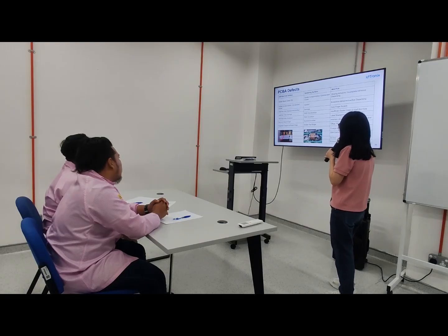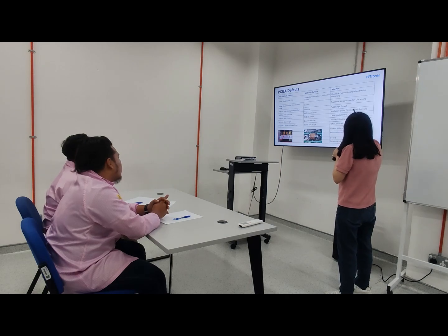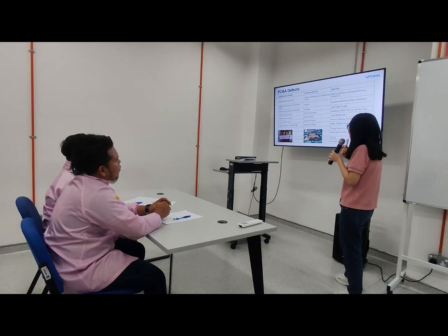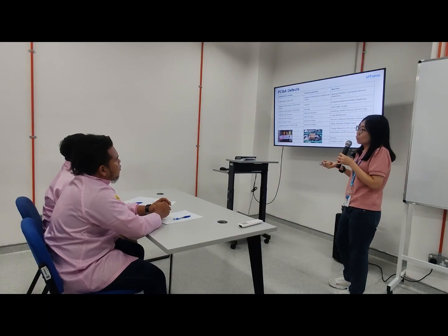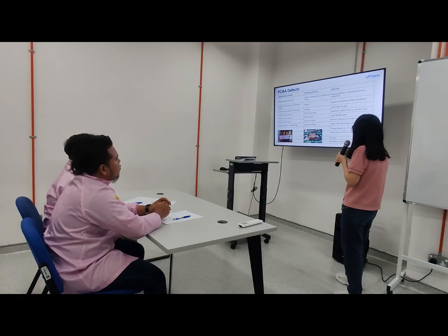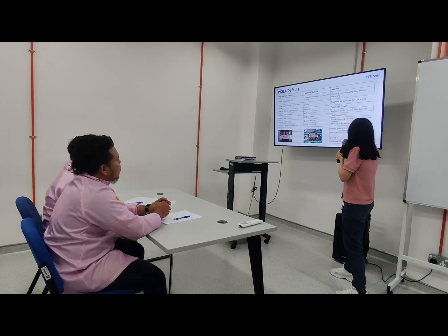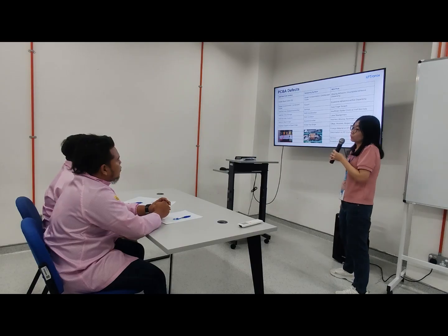Then PCIe, this is one of our products. For this product, we have the missing adhesive, then excessive adhesive, extra glue. Then we have gold finger scratch, insufficient solder clamps, label misaligned, incorrect, missing, reverse, incomplete label, offset, burger label, foreign material, deformation on RF connector, dented, excessive solder.